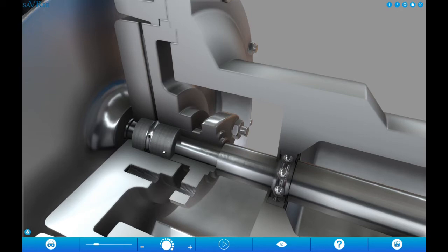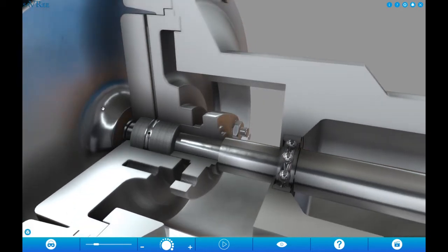What will happen when it becomes loose? The water will start dripping out at a faster pace. So you will have a lot of water coming out, not just a few drops. Comparatively, the general standard is not to have more than 2 or 3 drops per hour. But if you have loose packing, you will probably have a lot of drops of water coming out of the packing.